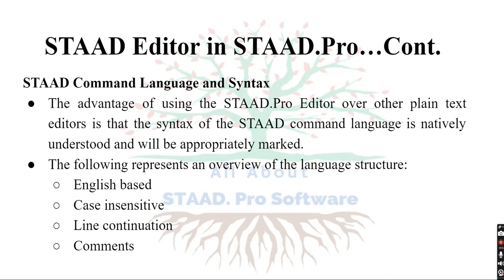Second one is case insensitive. Input data is not case sensitive, which means we can use either uppercase or lowercase. Next one is line continuation, which means lines containing lists may be continued to the next line by ending the line with a blank and a hyphen. Some lists have special rules or considerations.